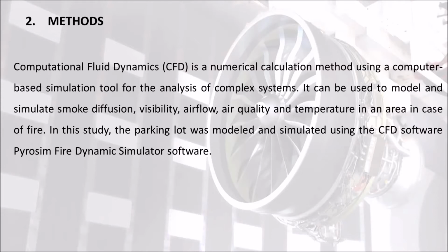And also in our methodology, a pressure-based solver has been defined for the steady-state model for this special case enclosed park area. And the volumetric transport model was also selected to describe the fire moving from a car with the inclusion of the diffusion energy source option. For turbulence modeling, we have selected the LES model, large eddy simulation model, to represent our turbulence.